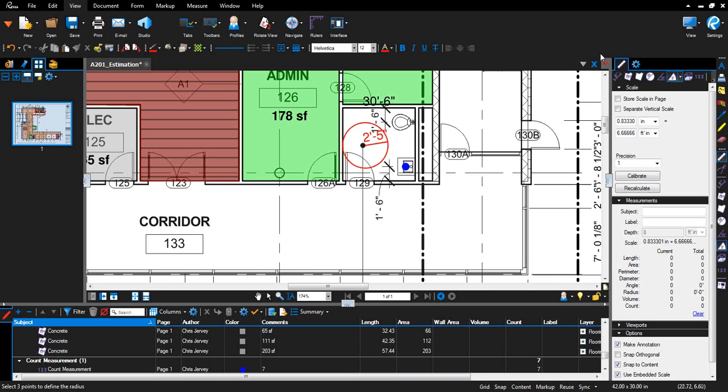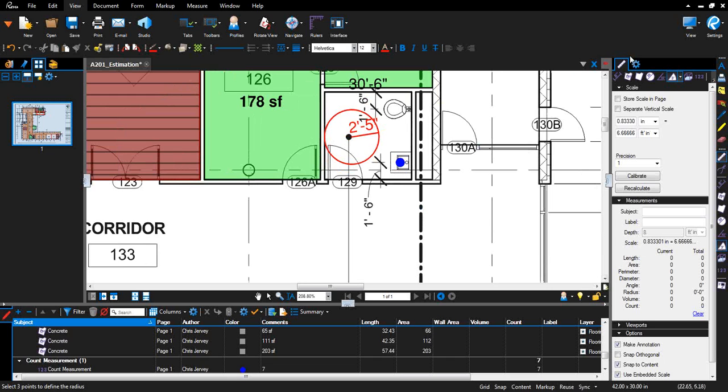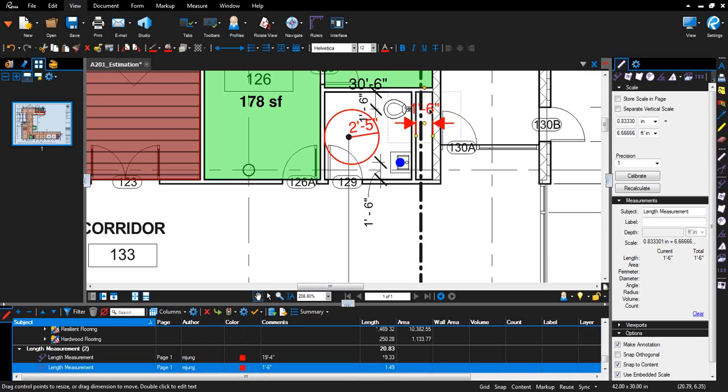Okay. Now, in addition, when you're measuring small areas, the length measurement has also been updated to allow you to more easily see length measurements in small areas. Previously in Revu, these were all sort of scrunched into that area. But now you can take that measurement and move it right off to the side, even rotate it. You make your takeoffs look nice and pretty like you would in any other takeoff program. You can see that measurement now is clear to read and looks quite professional.